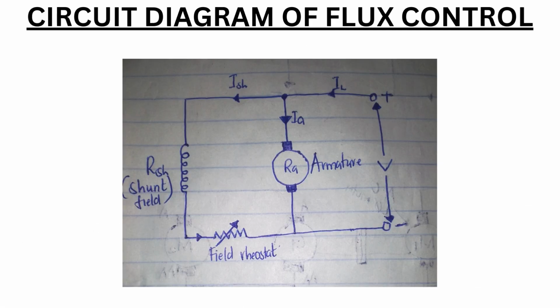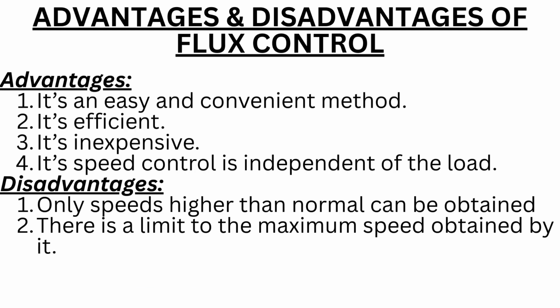The below is a circuit diagram of flux control method. The field rheostat is connected in series with the shunt field winding. Let us now look at the advantages and disadvantages of flux control.